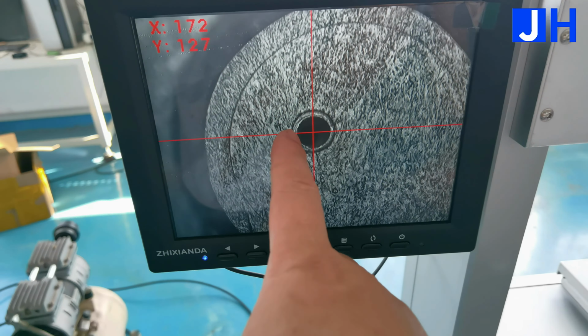Next we want to set the height of the coordinates Z-axis. We are going to set the assembly height of this screw nozzle. Set this nozzle height. First open the navigation interface. Click to go down. Find this user level operating parameters. Then click OK. Find item 9 settings visual camera parameters and click OK.